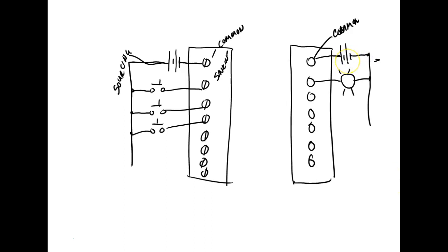This is a symbol, by the way, of a DC source. That could be a battery. Most people say it's a symbol for a battery, but it's a DC source. This guy right here would use the same symbol, but it would have an arrow through it. Anytime you see an arrow drawn through an electronic device, it means it's variable. The small line is the negative side of the DC source, and then the long line is the positive side. Now, normally each one of those lines is supposed to represent a cell. But normally on a PLC.